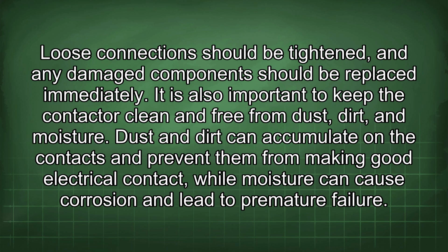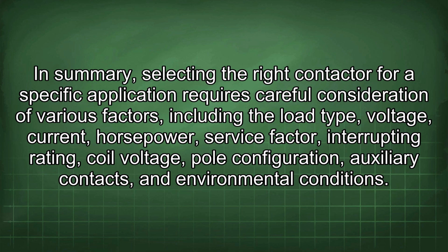It is also important to keep the contactor clean and free from dust, dirt, and moisture. Dust and dirt can accumulate on the contacts and prevent them from making good electrical contact, while moisture can cause corrosion and lead to premature failure. In summary, selecting the right contactor for a specific application requires careful consideration of various factors, including the load type, voltage, current, horsepower, service factor, interrupting rating, coil voltage, pole configuration, auxiliary contacts, and environmental conditions.